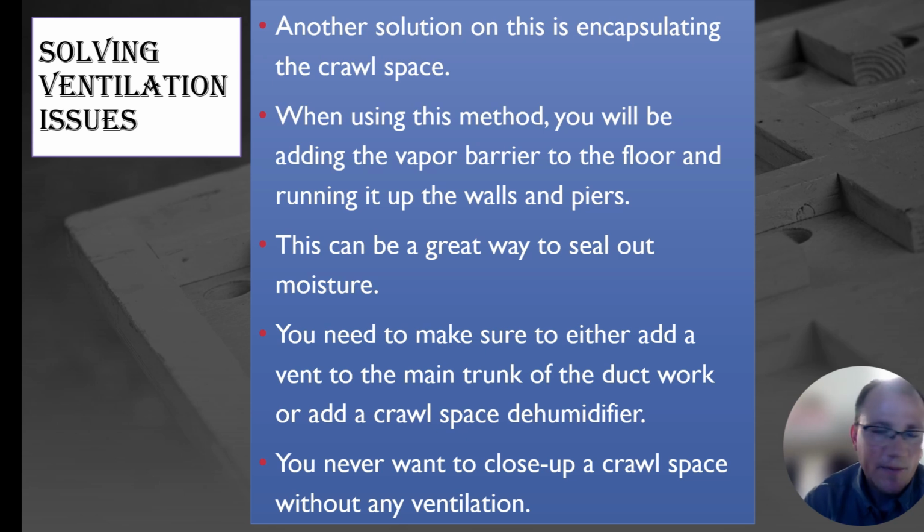And obviously a crawl space dehumidifier is not a bad idea. That's going to draw the moisture out of the air. One thing you need to do though, is have a positive drain put in at a low spot in the crawl space where that moisture can drain from that dehumidifier. It's definitely not something you want to go down yourself and have to worry about or dump water out of. But just keep in mind, you're going to need something moving air around. You're going to need something to dehumidify. Never ever close up a crawl space this way. But as far as solving moisture problems, I've had my best luck when encapsulating the crawl space and not allowing the moisture to get in the first place.